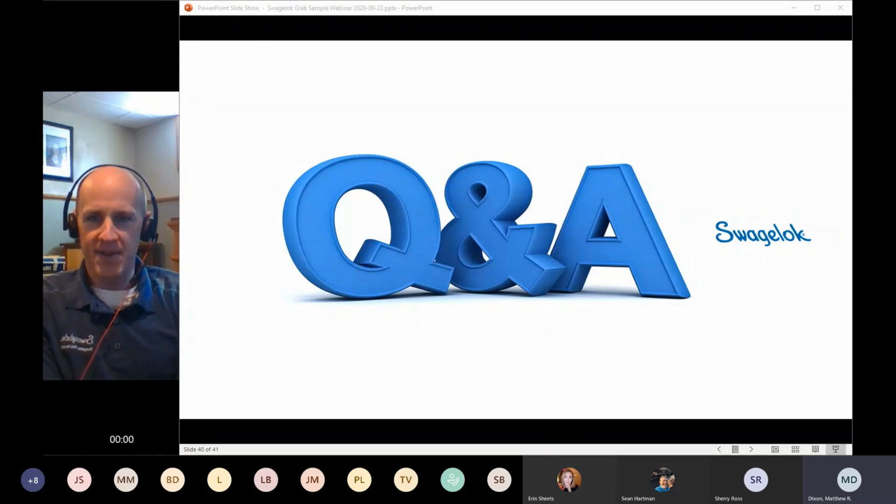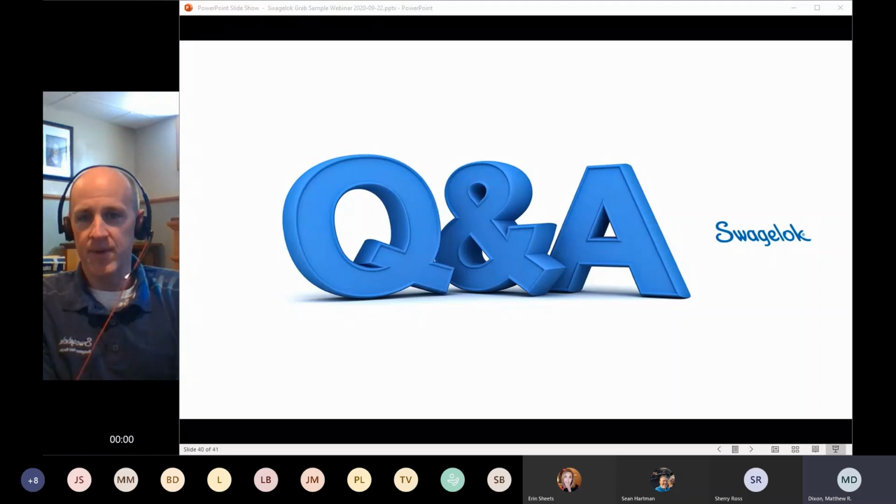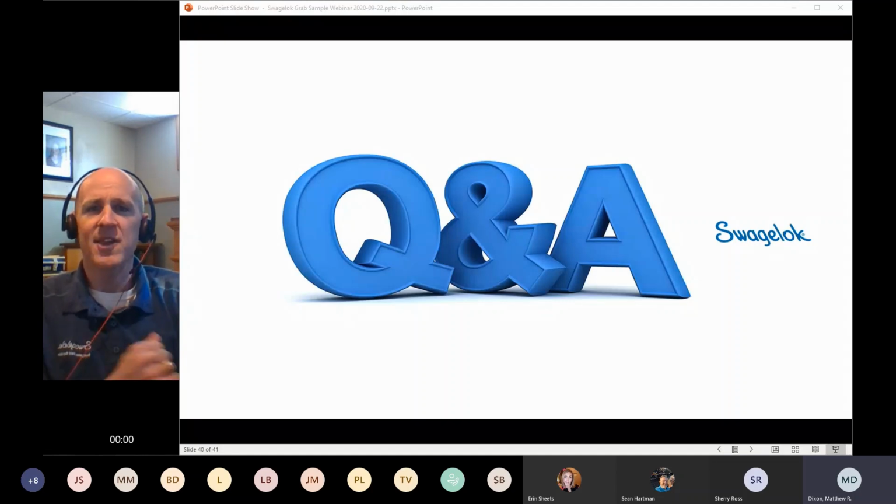So a bottle sampler, we have heard of some customers doing that. It's definitely not something we would recommend. We would definitely go with the sample cylinder. At that point, it's a question of chemical compatibility with the materials of construction. Pyrophorics tend to be somewhat reactive, obviously, so we want to make sure that the elastomers and the metals that we're using are compatible. Depending on the specific one, we would have to look at that for compatibility.